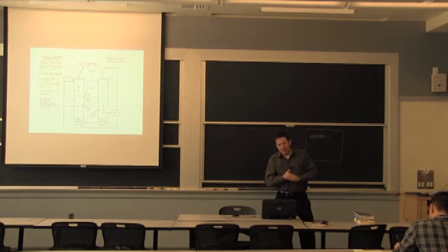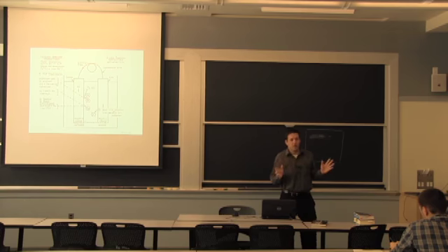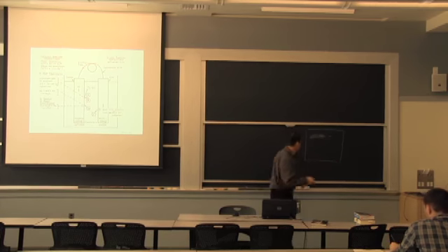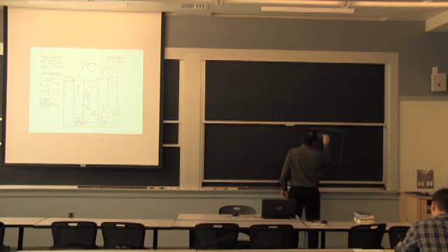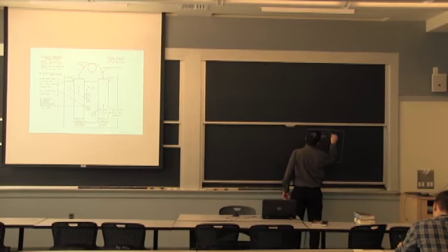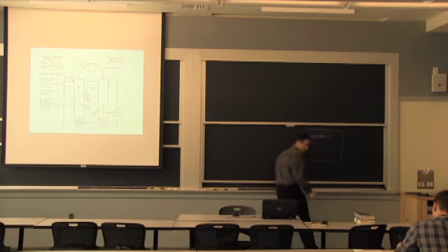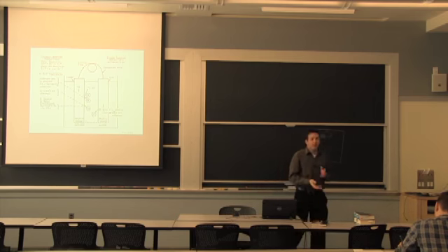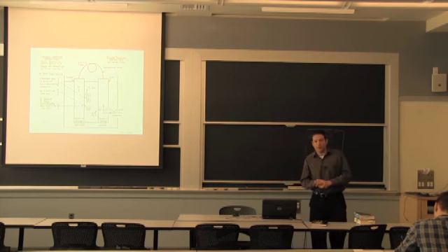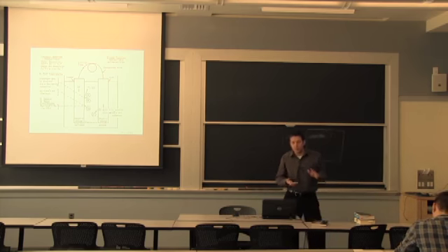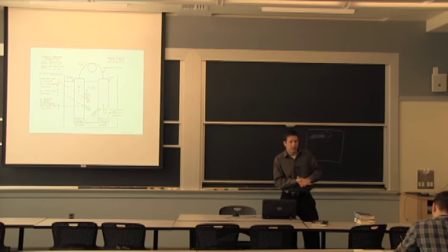So it may help you think of it as there's only one thing going on here. It's an exchange of electrons. So that goes through the metal itself. And then you have an exchange of ions as well through the solution. It's always the case, even if you have a single piece of metal. It's the case when you have two pieces of metal that are the same in contact. That's our crevice corrosion. And it's the same when you have dissimilar metals, and that's our galvanic case.